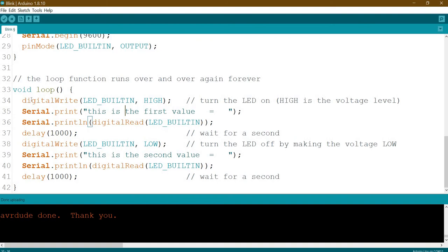Because when the code is running and comes to execute this, it takes time to send the data through the RX/TX pin on the MCU, to the UART, or to the FTDI converter, which is UART to USB. Then the USB will send it to the serial on your IDE environment, and the IDE sends an acknowledgement, received. So it really takes a long time and exhausts your memory.